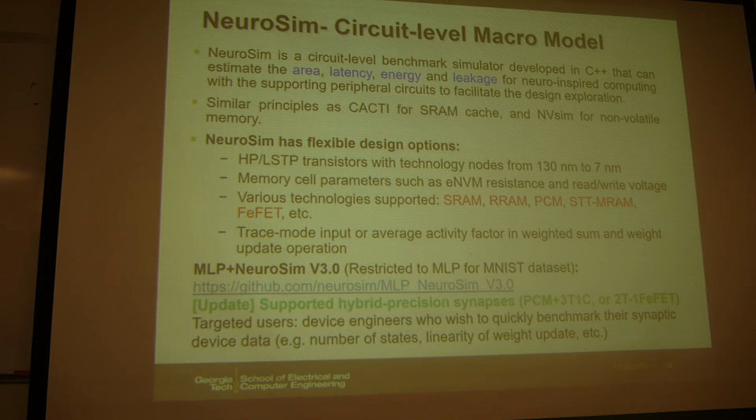We are going to model the whole accelerator's performance using a similar approach as NVSim, but with additional circuit modules, because when you do computation you need additional modules, for example, accumulation, pooling, activation, and so on. So we have those available in this model.